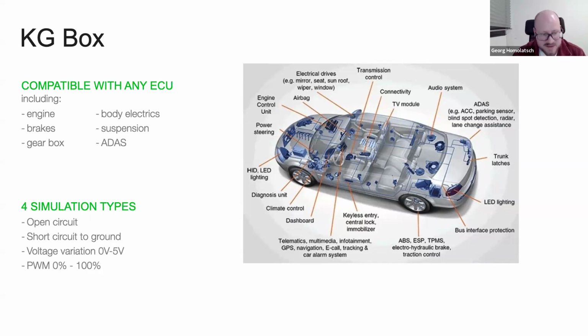So with these two advanced simulation options, you really can create quite advanced scenarios. And you can also show to the student, and this is for more advanced students, the different strategies of the vehicle. How does the vehicle react at 2 volt, at 3 volt, 5 volt, right? At what point does a fault code come up in my diagnostic scope? At what threshold does the vehicle change behavior? So this can be very interesting, especially for more advanced students.